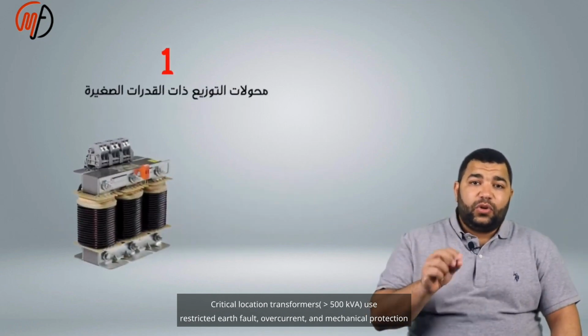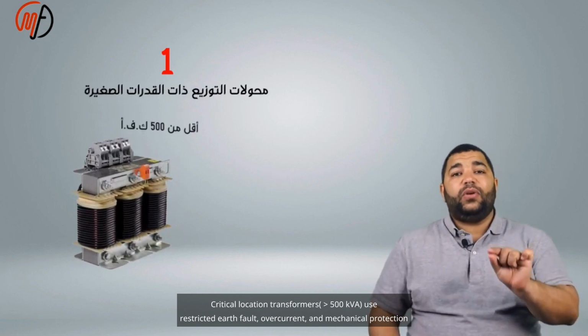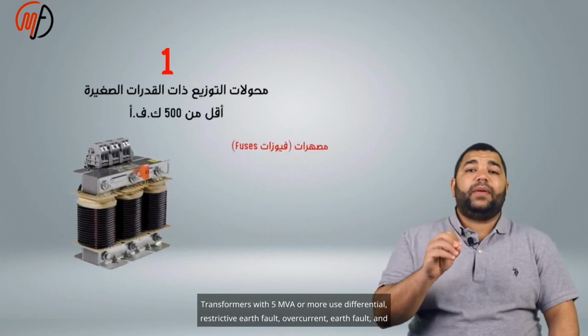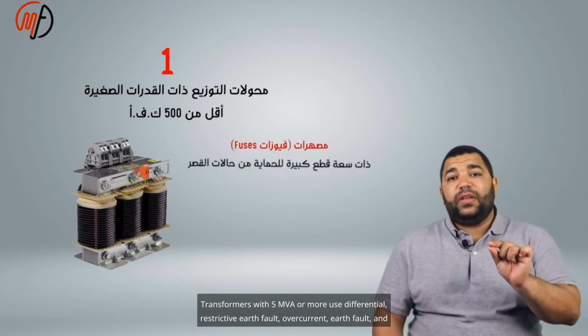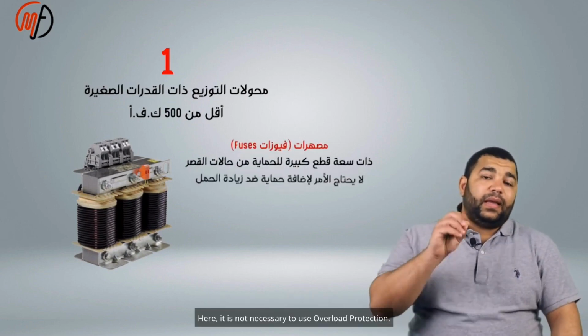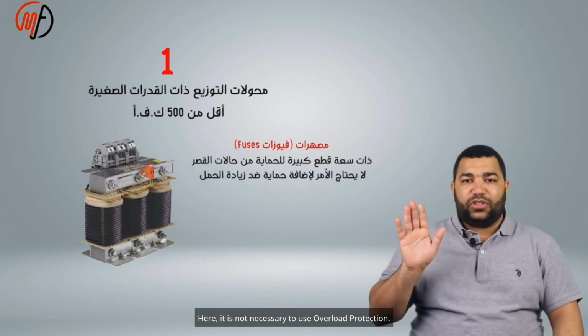Critical location transformers, above 500 kVA, use restricted earth fault, overcurrent, and mechanical protection. Transformers with 5 MVA or more use differential, restricted earth fault, overcurrent, earth fault, and overflux protection. Here, it is not necessary to use overload protection.